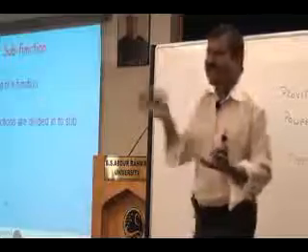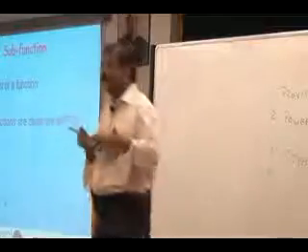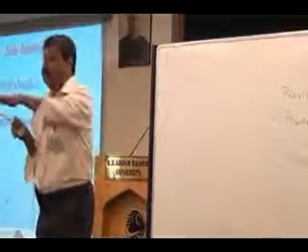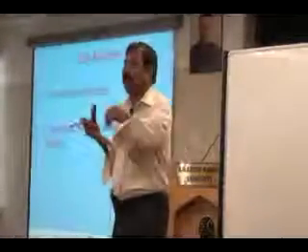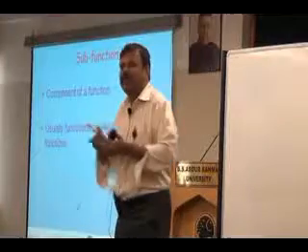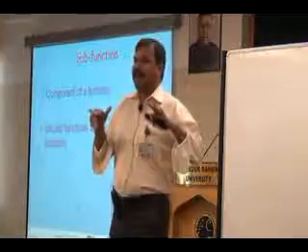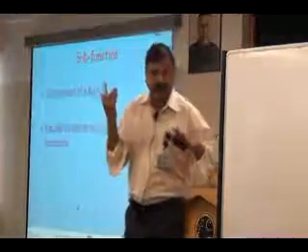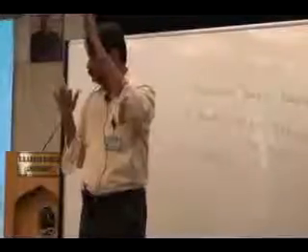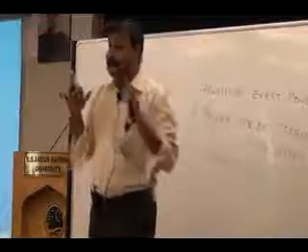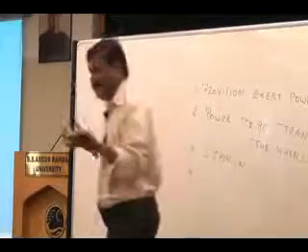What the gear does is, it does some trade-off between speed and torque. If I am traveling on a level road, I need not have so much torque because it is only the friction that is to be overcome. So the speed can be increased. For the same power, the torque supplied is reduced and the speed supplied is increased. If I am going uphill, the torque required is so much, so the speed is reduced, the power remains.